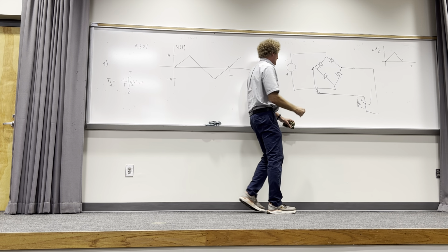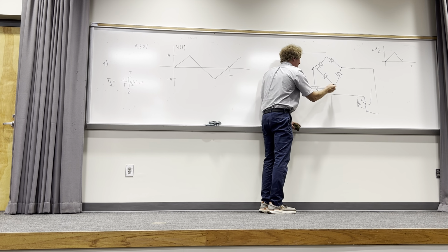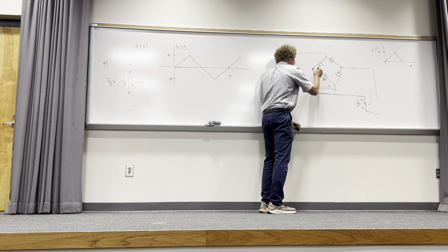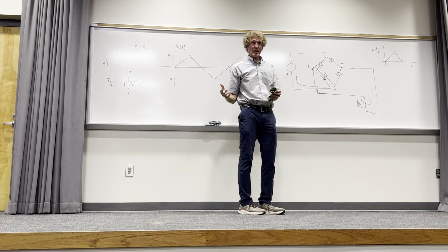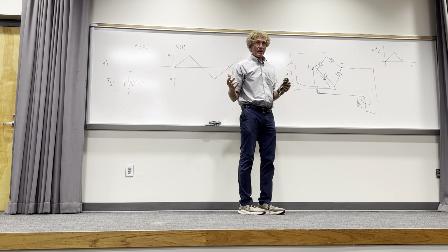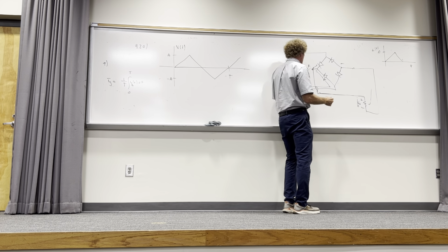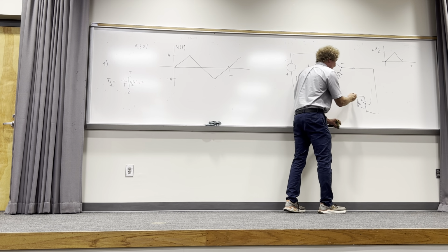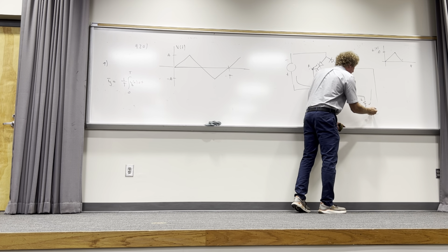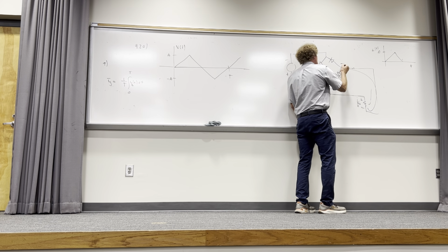When it's negative, it comes down here, right? It can go through this one, but it can't go through this one. So it comes this way. Now it's still coming out. You can label that positive and the negative terminals, but this is full wave rectification in essence. Comes down here, right? Hits this, comes down. It's still got the same polarity, plus to minus, and then it returns, but it returns this way.